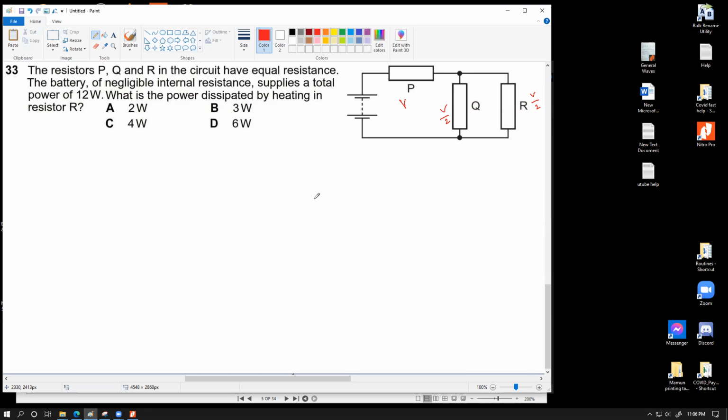If you observe this thing in terms of combination, here we have a series circuit where one of the components of the series circuit is a parallel combination. So here you have one component and here you have one whole component. So voltage will be shared over here. Because this component has double the resistance compared to this combination, this will definitely eat up double the voltage compared to the individual voltage of both of these. Make sense?